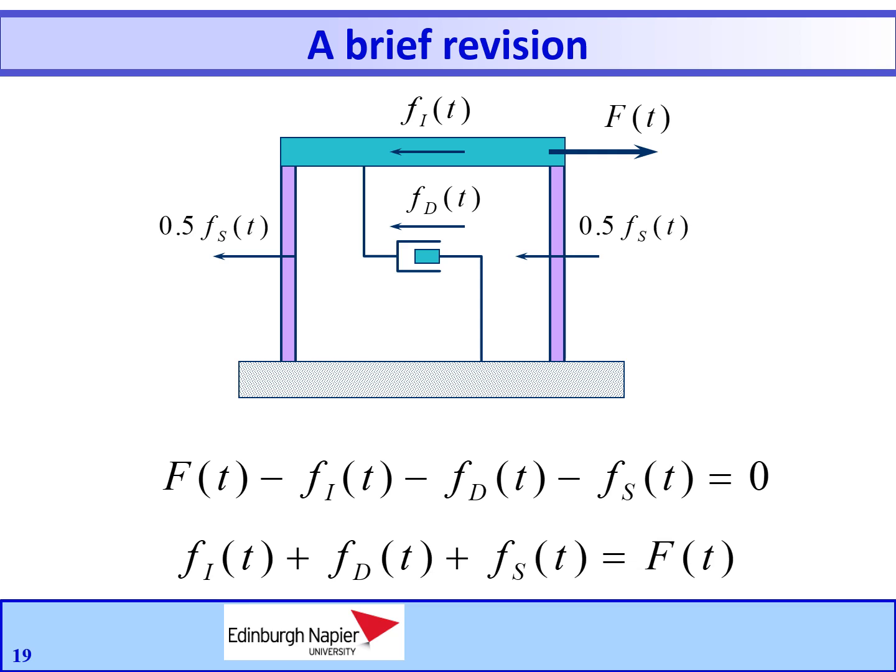In actual structures, many mechanisms contribute to the energy dissipation. In a vibrating building, these include friction at steel connections, opening and closing of microcracks in concrete, and friction between the structure itself and non-structural elements, such as partition walls. It is impossible to identify or describe mathematically each of these energy dissipating mechanisms in an actual building. That results in the damping in actual structures being represented in a highly idealized manner.